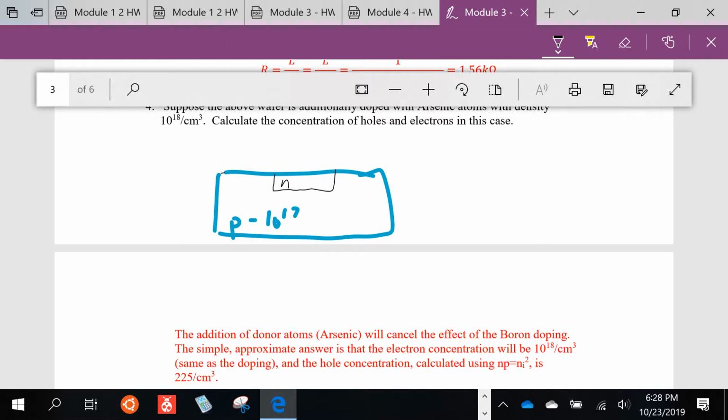And if you don't remember the name of the process, that's okay, but conceptually what's being done. Think back to originally: you get your silicon, silicon comes from sand, right? What's the next process when you're making a silicon wafer? Melt it down and make an ingot. That's the one, the melting down. That's called the Czochralski process. Do you guys remember this? Yeah. Okay, good. You scared me for a second there.